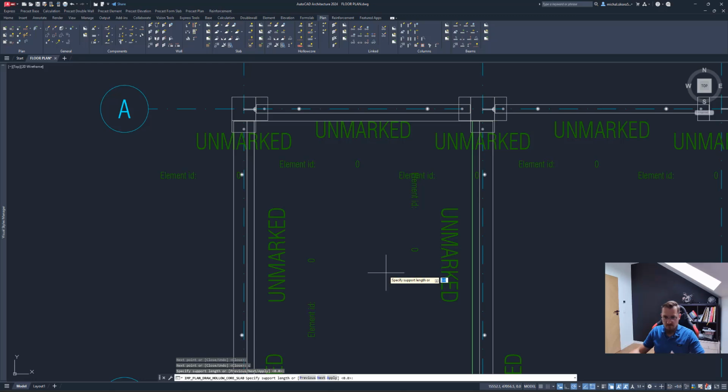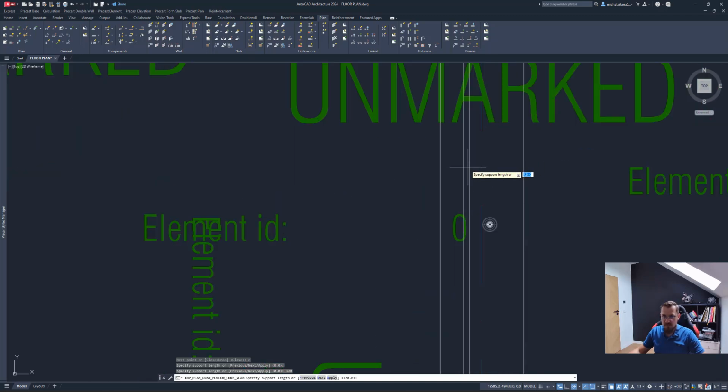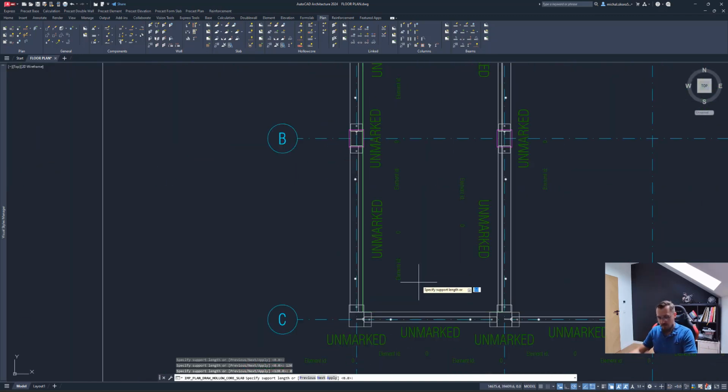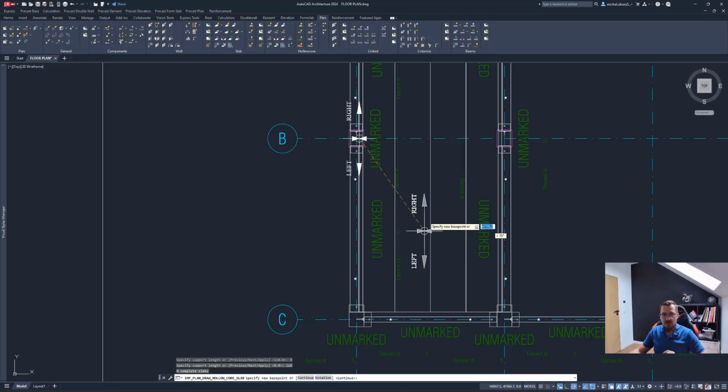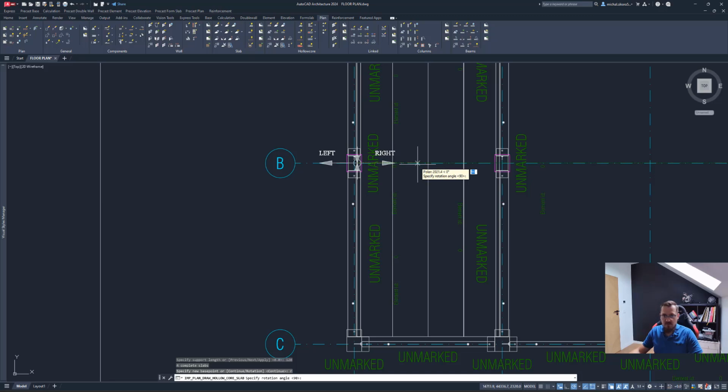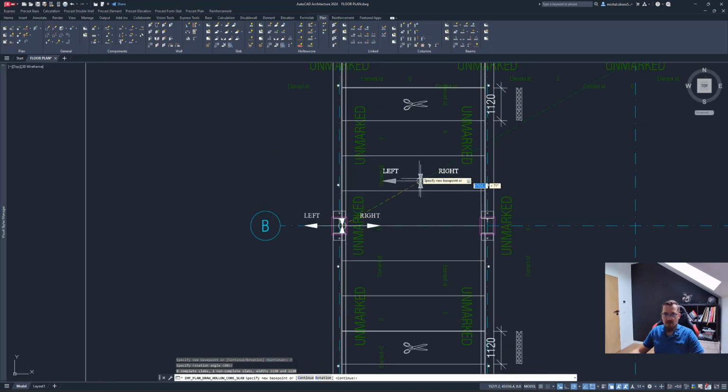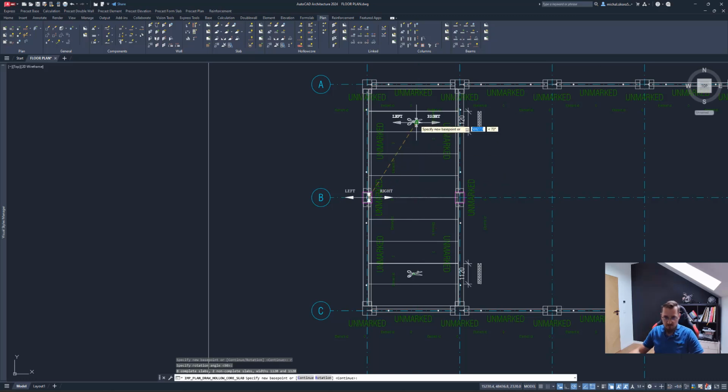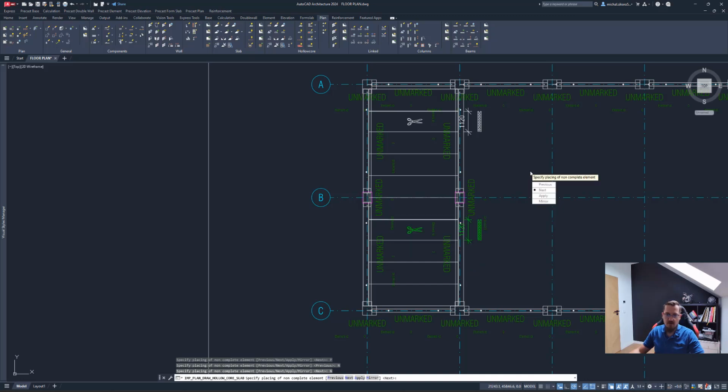Now this edge is highlighted green. Let's go and add that 120 mil support. As you can see, the line extended. Next edge, that's going to be 0 again, and 120 again on that last edge. I'll also rotate the hollow cores, and you can immediately see in the preview there will be some cut hollow cores to fit in as many non-cut hollow cores as possible. So I'll just accept that rotation, and I can specify if I want this cut element to be at this location, or just move it around to different locations, right? So you can specify that wherever you want that to be.